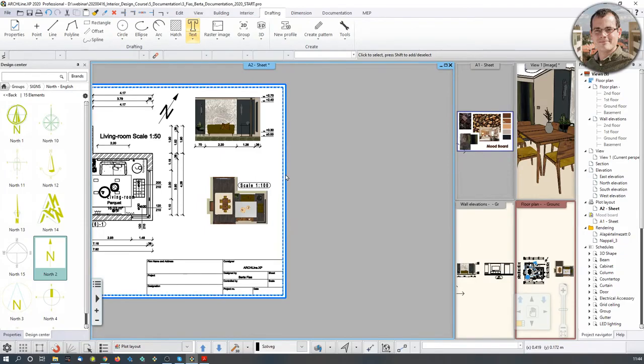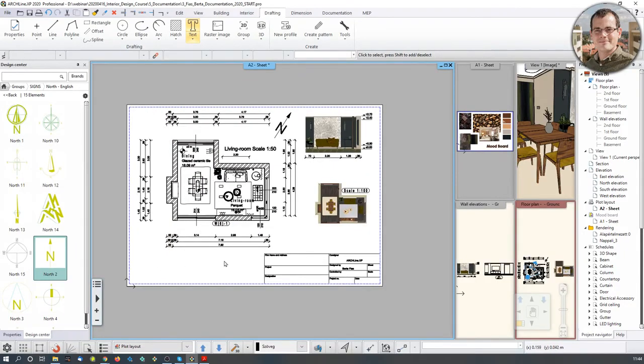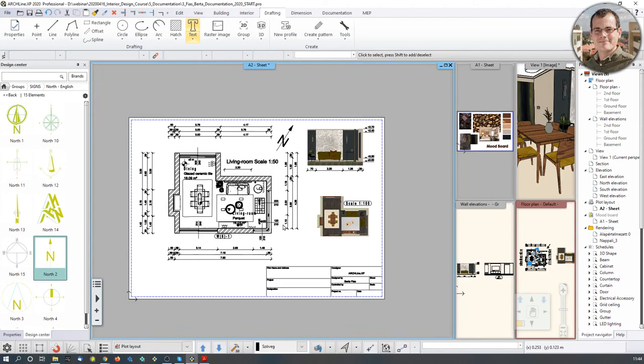Point to remember here, on the layout everything is scaled down. So if you put down something with its original real world scale, it's going to be too large. Similarly, if you are using drawing elements on an actual 1-to-1 scaled working environment, it's going to be too large. These are the only things to remember regarding that. I already showed you how to refresh the layout.